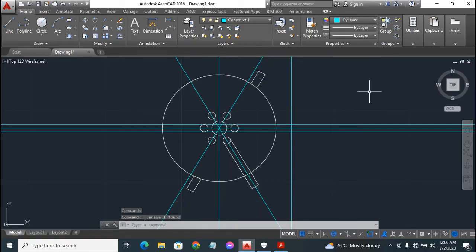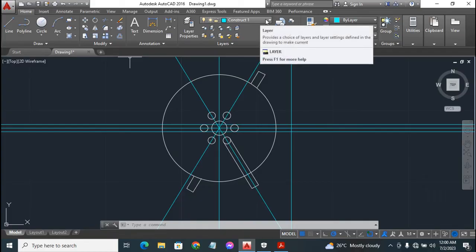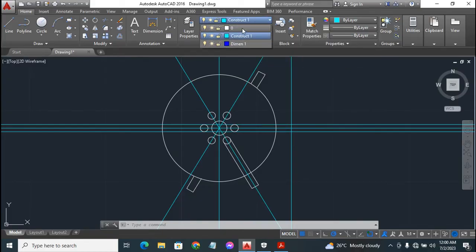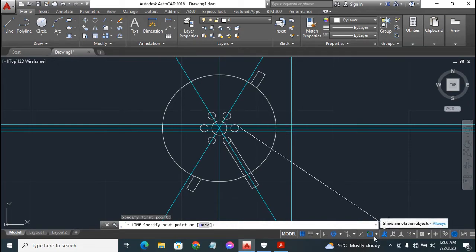So next up, we'll use our main layer. Go back to our main layer to draw in those tangent lines connecting the cycle and the point of intersection of those construction lines. So go to the layers ribbon, click on the drop down of the layers ribbon, click on the 0 layer, which is our main layer, then straight back to our drawing ribbon, click the line tool, then back to our cycle, click on the tangent point here at the top of this smaller cycle, extend it back to this point of intersection, which is not locking because we don't have intersection turned on.